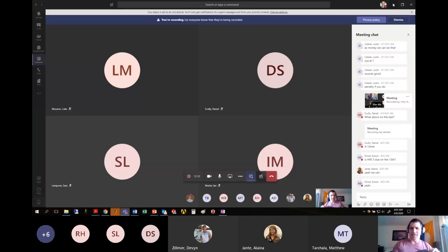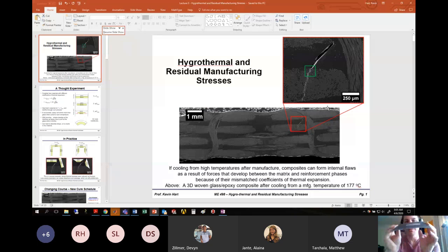But okay, good. All right, so this composite is a composite we manufactured, and remember, it had this like residual curvature. So if you can kind of see this, it's got sort of this like curvature that's sort of like pointing in this direction, and we have this like residual curvature to this piece. Okay, there's also probably residual strains that are sort of longitudinal that we can't really interpret because we didn't really know the original size of the piece.